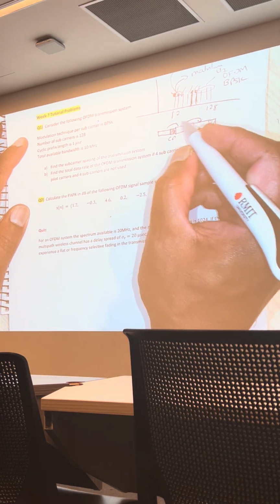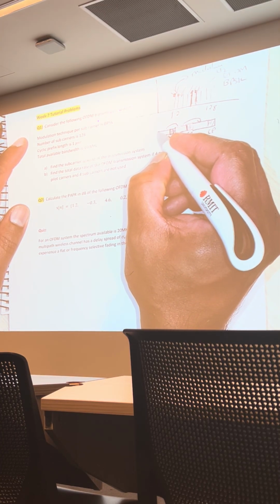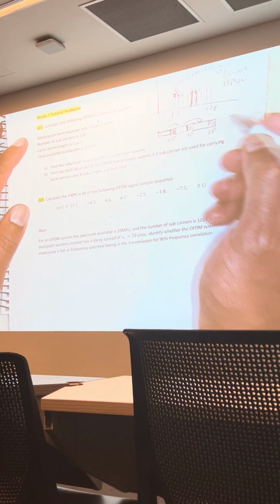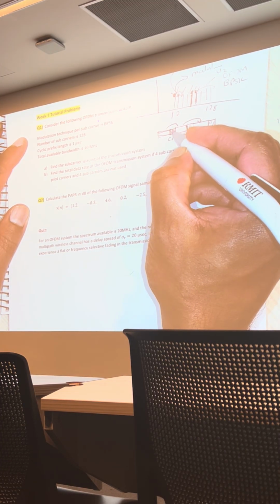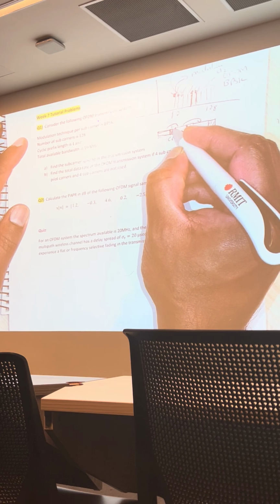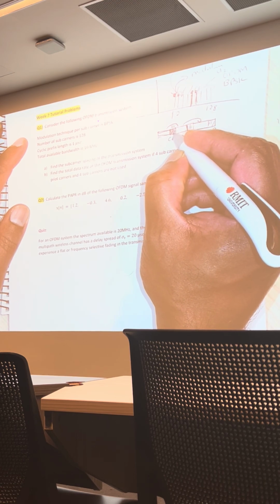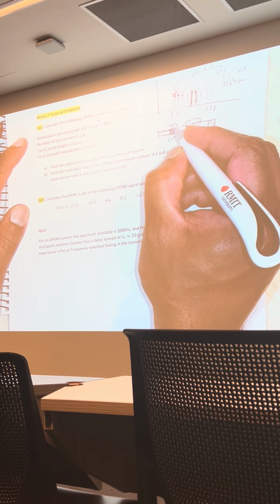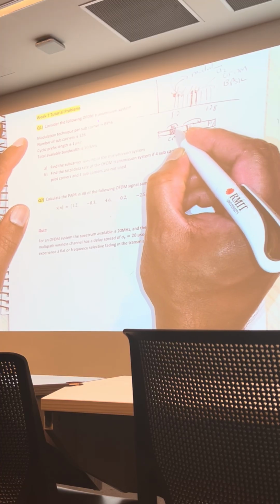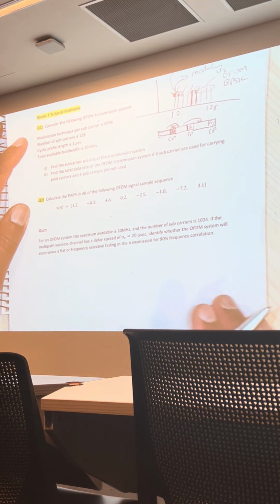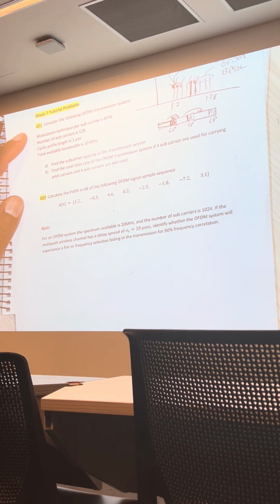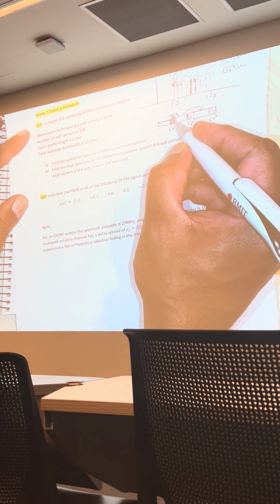so that when we have a multipath effect, we know that the first ray comes along and then copies of the same come afterwards because of the multipath delays. So this guard band will make sure that it has sufficient time to receive the multipath component before it interferes with the next symbol. Okay, so that's what's called a cyclic prefix.